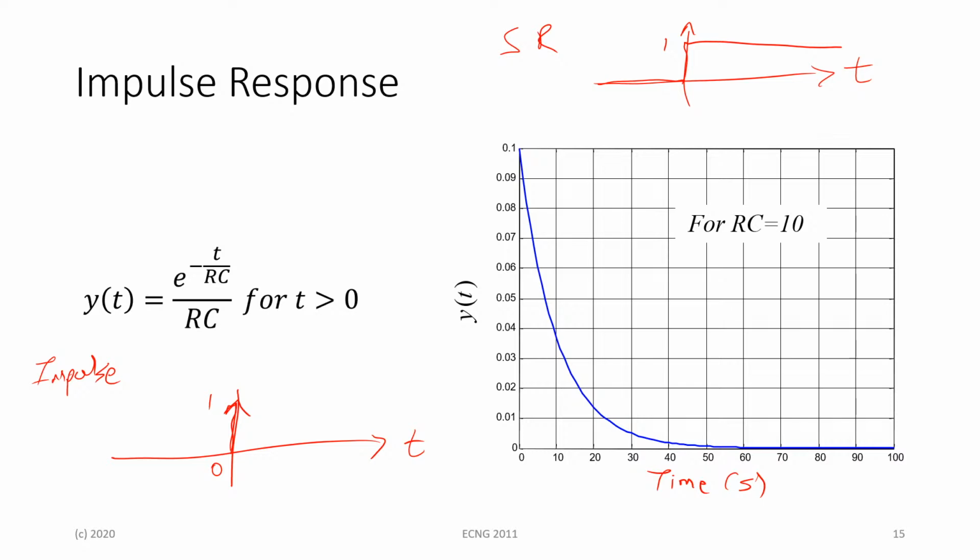Will the impulse response curve be mirrored? Yes, you can say in this particular case it's mirrored, but remember we're dealing with a first order system here, where we only have all our terms going up to the power of 1. What we're going to see later on when we go to a second order system, where we have the power of 2 involved, and when we go up in powers for polynomial systems, is that the responses change into different behaviors.